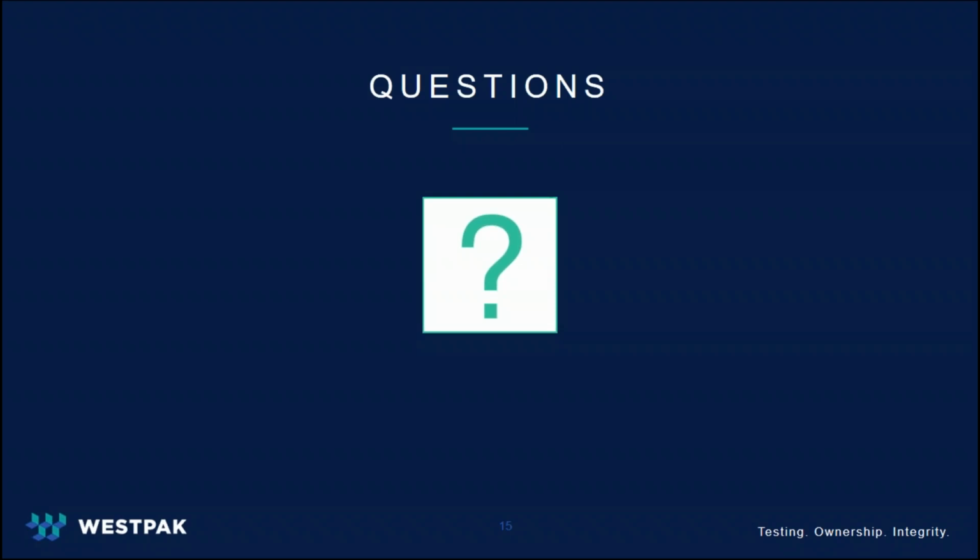Let's see. Another question about 4169. What's the appropriate sample size for ASTM D4169? The conundrum, sample size. It's really up to you to determine the confidence and reliability level that you want for sample size. We did a webinar, Tim, correct me if I'm wrong, I think it was last year. We had a statistician come in and do an official sample size webinar. And then from that, we developed calculators that you could find at WESTPAK's website to calculate what sample size should be. So really the sample size is up to you, and it depends on the confidence and reliability level that you're looking for.